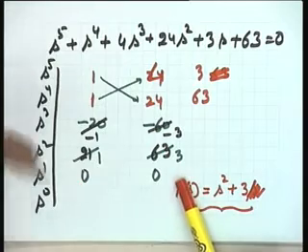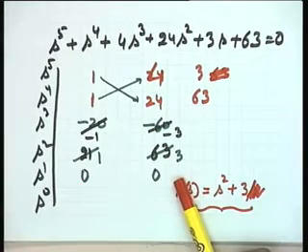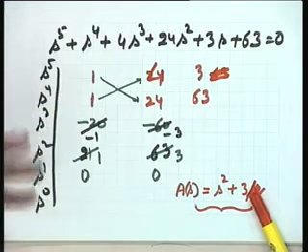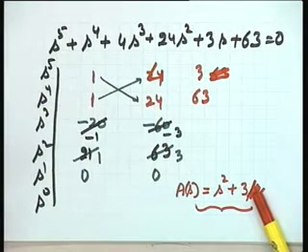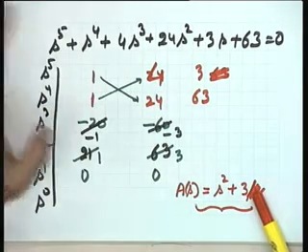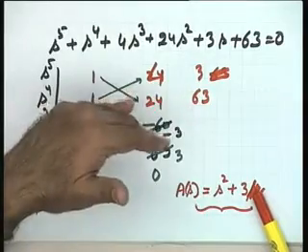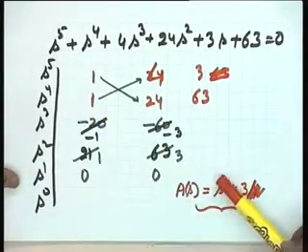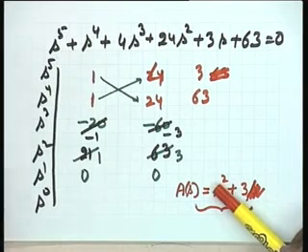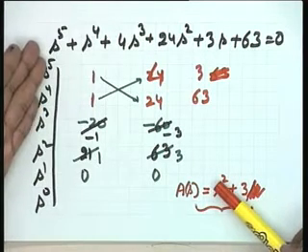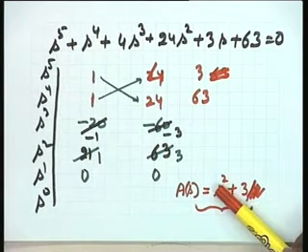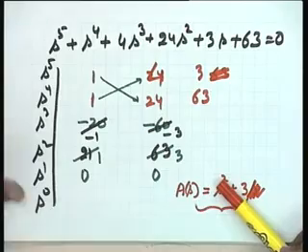Naturally such a situation will not arise, because that polynomial will not have this type of situation, and therefore the conclusion regarding the number of roots of the remainder polynomial in the left half or the right half plane has to be taken into consideration before you declare this system to be marginally stable or unstable. This system at the most can be marginally stable, it cannot be a stable system; this has been established. You simply want to examine whether it is unstable or not.